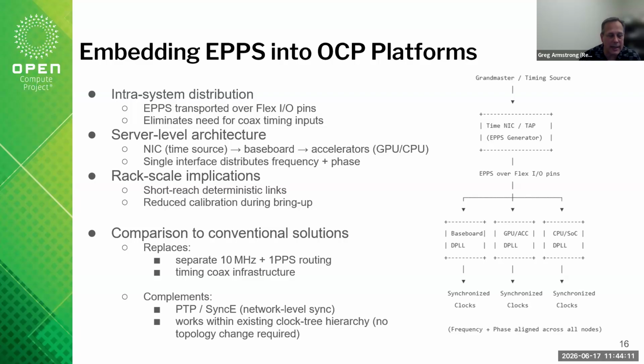And 10 megahertz really isn't a fast signal, right? Like you have 100 nanoseconds in between cycles, right? So you really only have to splice that up into like maybe 10 nanosecond chunks. Well, most analog circuitry today can go well beyond that. So that is not a difficult thing, right? Most circuitry now, we talk about picoseconds of accuracies of measurement, right? So doing it into tens is fairly easy, and most off-the-shelf components probably can do it.